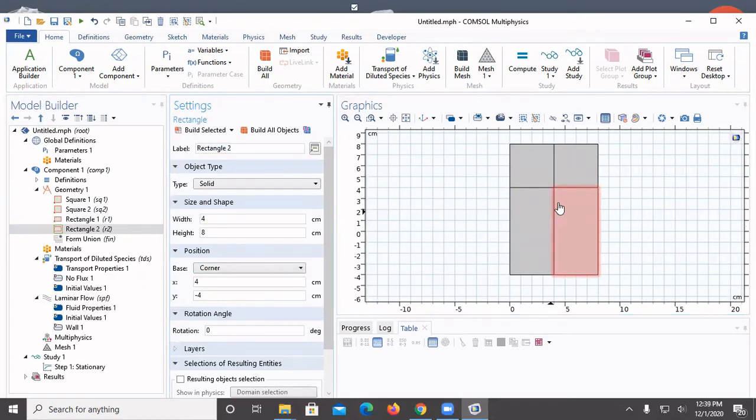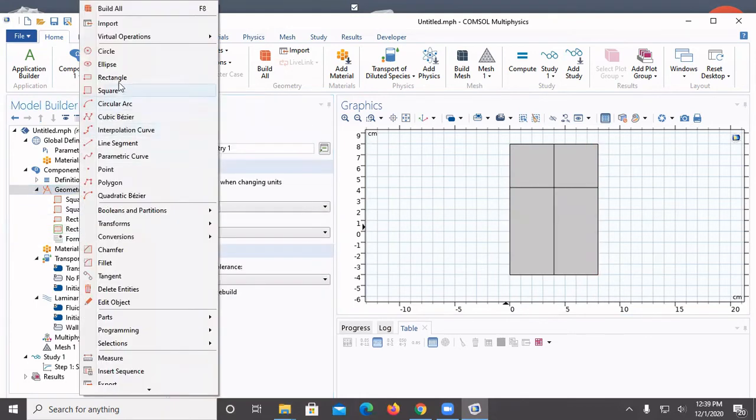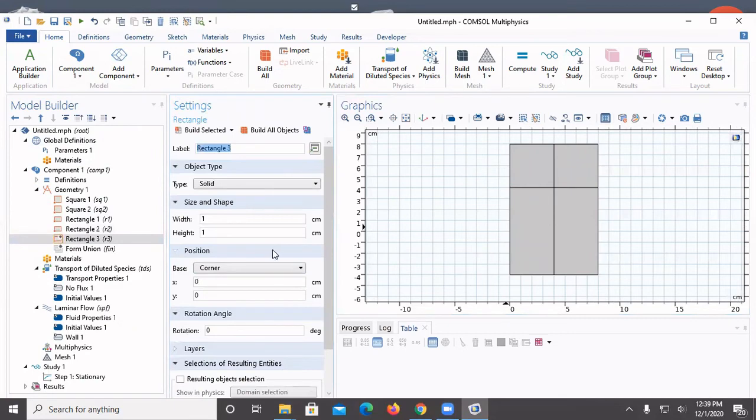So let's do that. We add 2 pulmonary veins to the left atrium. We'll add a rectangle that is 5 centimeters long and 1 centimeter in height, positioned at X at 8 and Y at 5 centimeters.